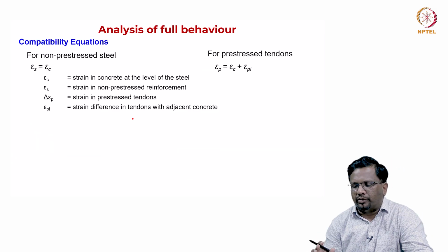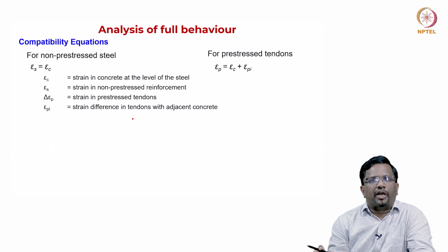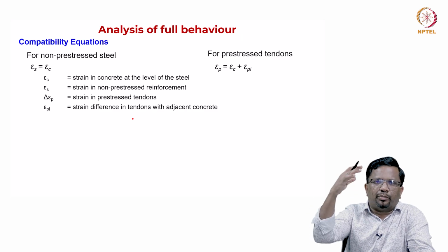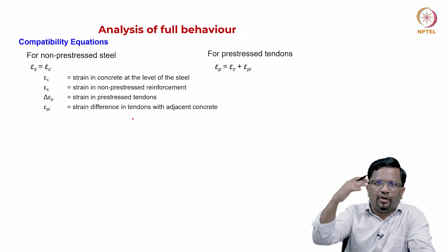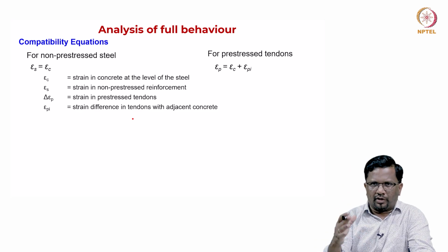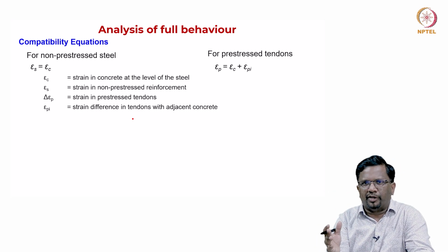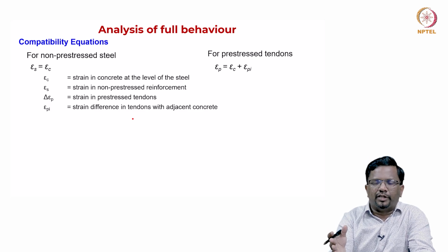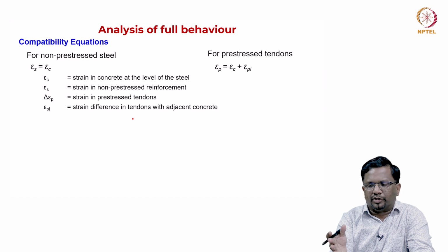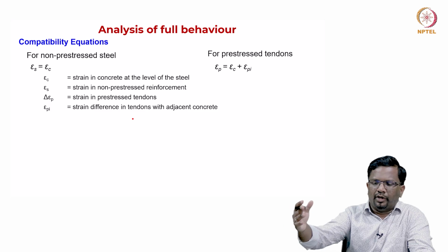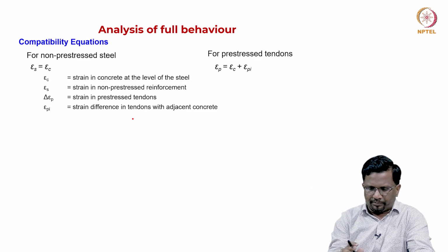Okay. So, now let us see the compatibility condition. In integrating the compression stress profile, we have difficulty. So, we found a shortcut to do it in a simpler way using equivalent rectangular stress block parameters. To ensure force equilibrium, C c, the compression force in concrete, is equal to the tension force in steel, so we need to calculate C c. That is why we did that.